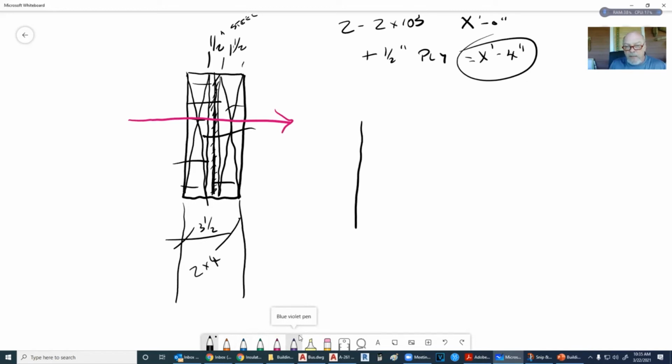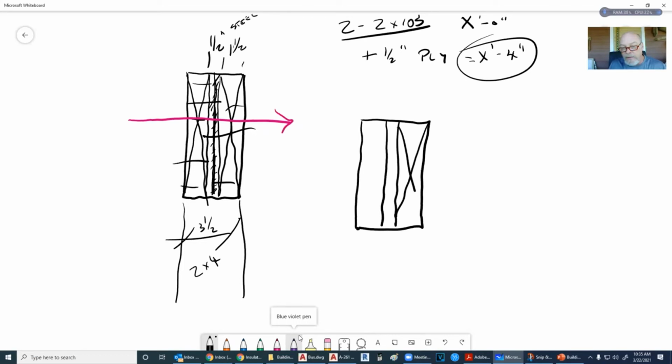So it became a secondary practice for us that if the code called for 2x10s, we'd put the two 2x10s together and then put blue board between them. I keep calling it blue board because it's now green and pink and all kinds of colors. It's extruded polystyrene, and when it was all blue, it was Dow extruded polystyrene, about the color of this pen. We would sandwich that together and think, oh man, we're good to go. It put in a thermal break, so when we had heat transfer, it hit this point and pretty much stopped.